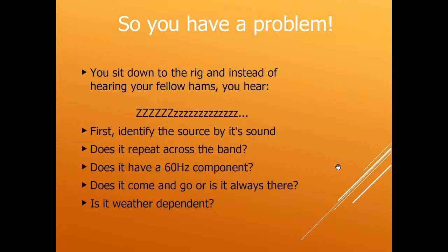Is it weather dependent? If it only comes when it rains, or if it only comes when it's dry and windy like today, that can be a hint that it's some kind of an event happening in the power pole, in the telephone pole power distribution systems. Sometimes the insulators get a crack in them, in which case, when the water gets in the crack, that can cause a problem. Other times, there can be a loose connection, in which case the water actually helps the connection and quenches the arc. But then when it dries out and the wind blows, it can make that connection come and go and make noise.